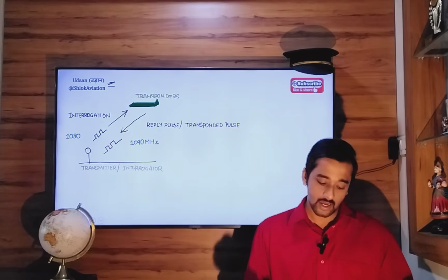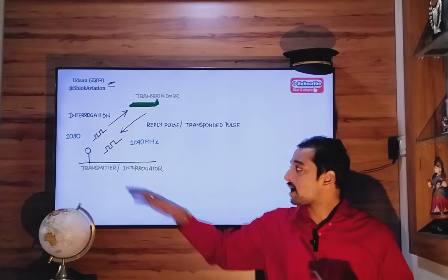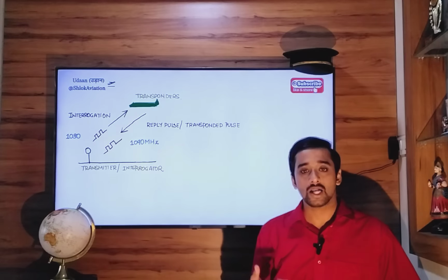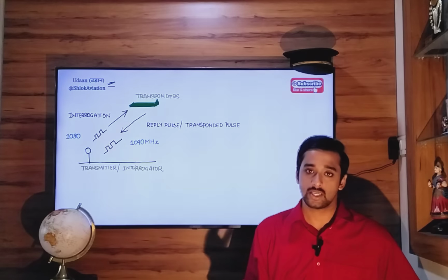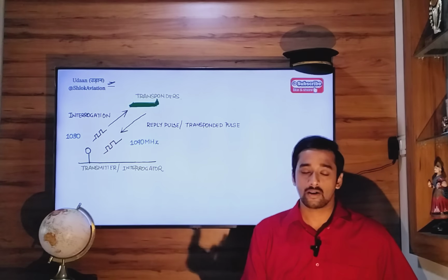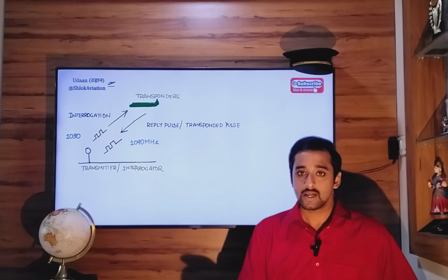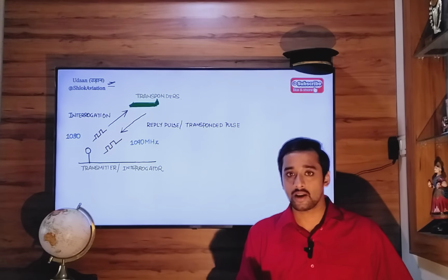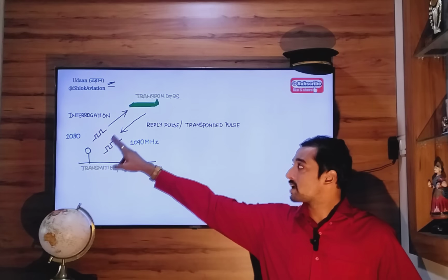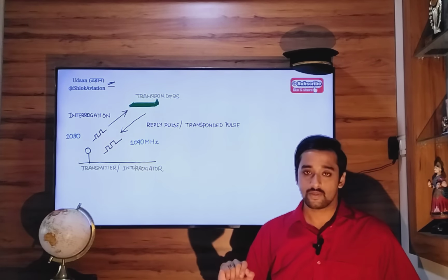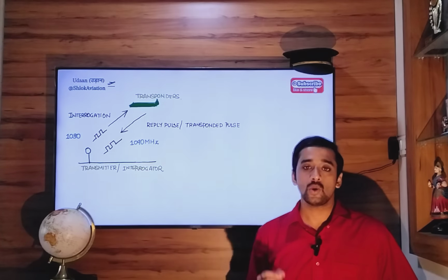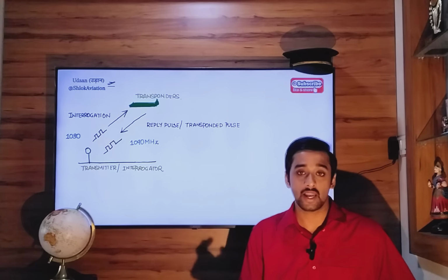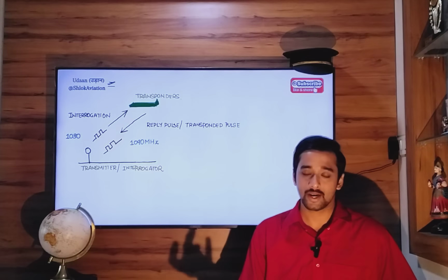But in case of secondary radar, we do not use echo principle. The ground station will transmit an interrogation pulse towards the aircraft. The aircraft will reply or answer to that pulse by sending its own information, its own unique pulse of radio energy. So there is no concept of echo in case of secondary radar, and that is why the transmitted frequency and reception frequencies are different. Since the frequencies are different, there is no concept of any kind of echo or reflection generated from any large water droplet in the atmosphere.